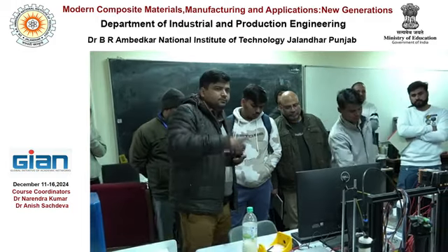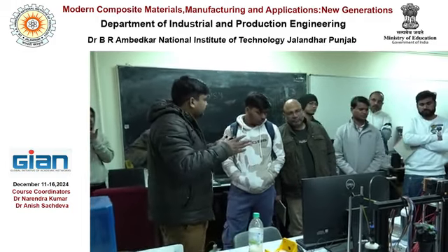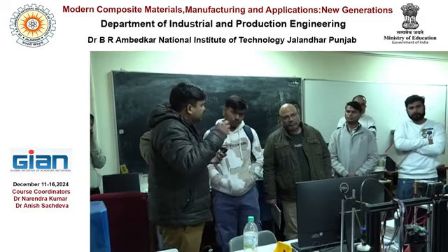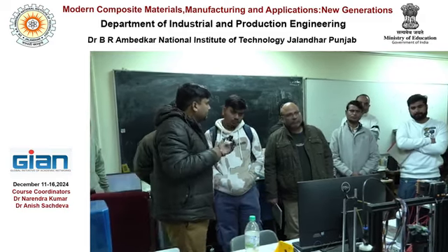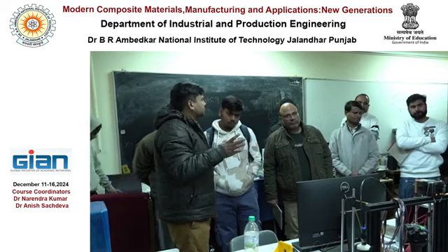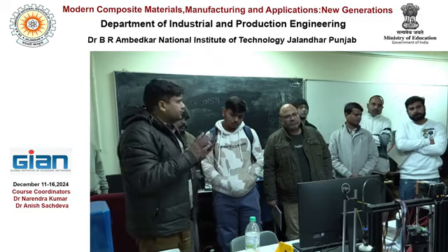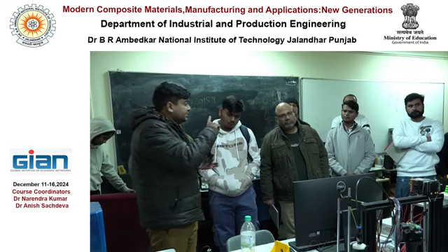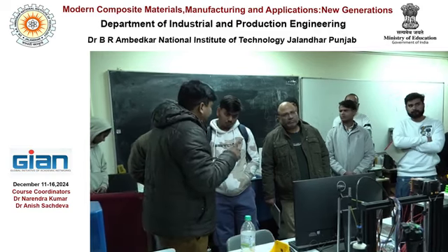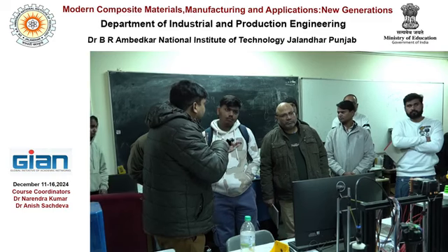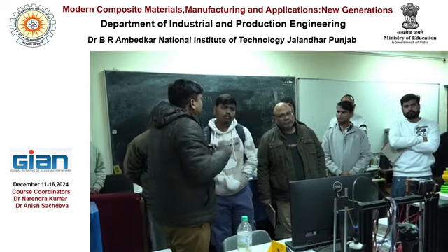So according to the requirement, we can change the orientation, right? According to the main requirement of the product, we can change this orientation. Now, once you finalize the orientation, see, orientation is very, very important. Why? Because the number of layers, how many layers there will be, depends on the orientation.